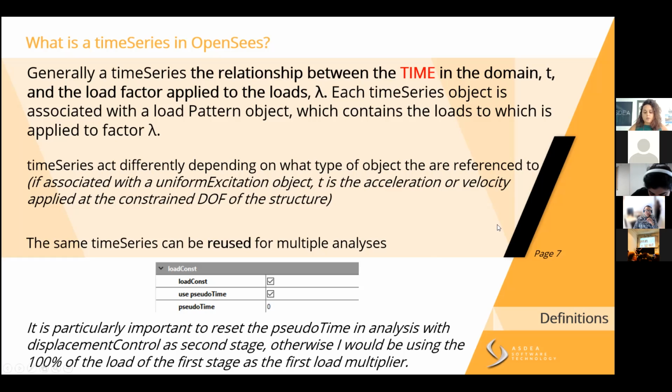This is particularly important to reset the pseudo time in analyses with displacement control, for example, because the second stage will be using the pseudo time as a load multiplier. So if you don't reset it, it will be like already getting to 100% and applying 100% of your displacement as the first step. So this is a bit confusing, I think, because we talked about pseudo time.